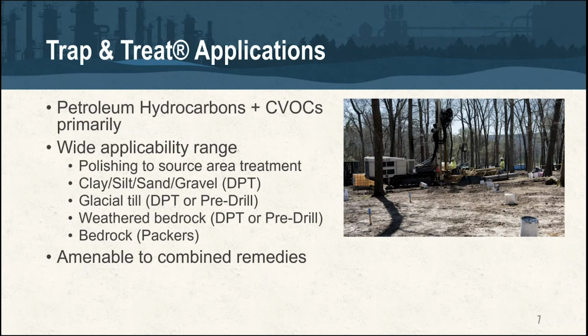If you've got equal mass in two theoretical cubes, one clay and one sand, the amount of material is going to be the same, because the loadings are based off of total mass. What may be different is the injection point spacing, which for these technologies is usually 5 to 7 foot on center. We can get as far as 10, but that's pretty rare.